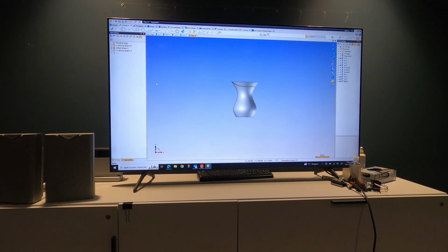And then you can trim by profile. Trim by profile, which is in surface. Make a right click directly on the line. And so the shape to modify is the first shape. This one. The sketch is already selected.